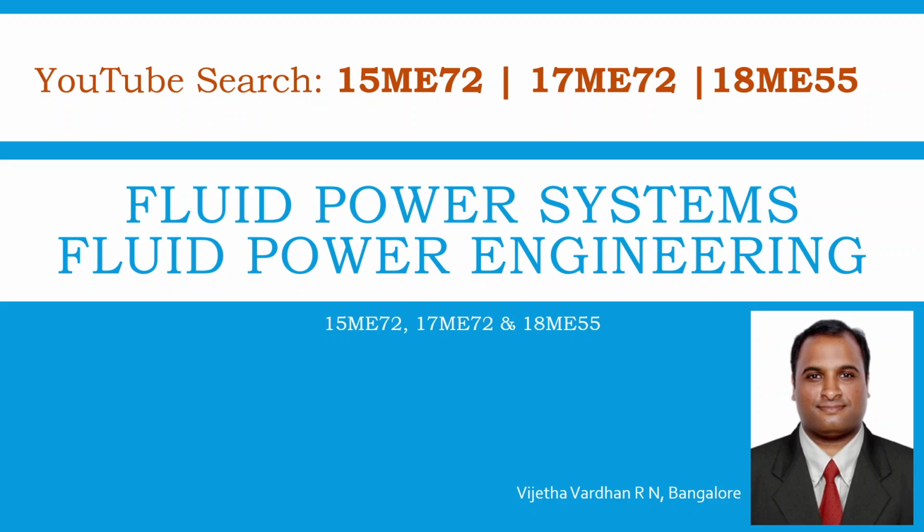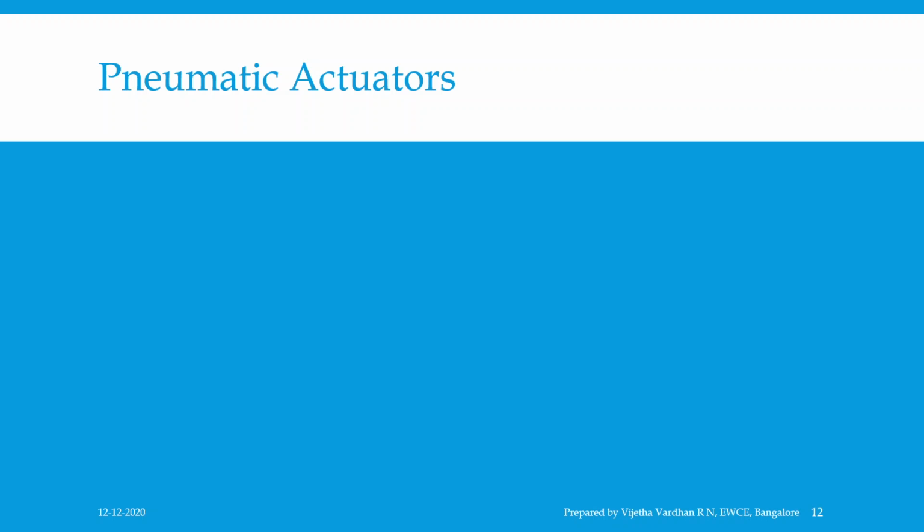Now let's start session number 39, which is based on pneumatic actuators. Actuators are those which have motion or to which motion can be imparted. If the motion is imparted by energy contained in air or gas, then it is called a pneumatic actuator. Pneumatic systems also use actuators similar to hydraulic systems, except air is used as the operating medium. Since the operating medium is air, pressures are lower and hence the construction is lighter.